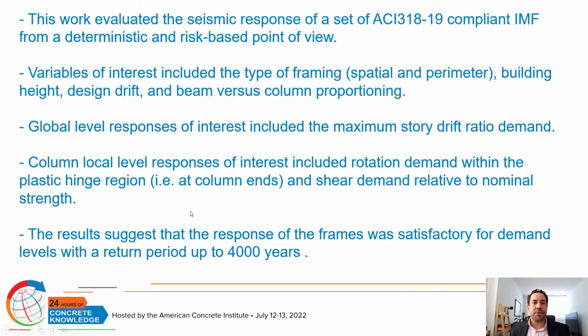The results suggest that the response of the frame was satisfactory for demand levels with a return period up to 4,000 years. So, for the type of frames evaluated and the limit of this study, we can say that the strong column weak beam provision might not be required by the intermediate moment frames under intermediate seismic hazard.